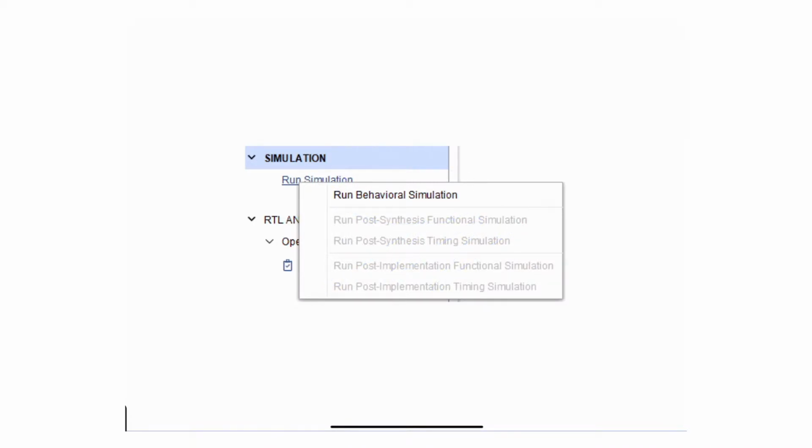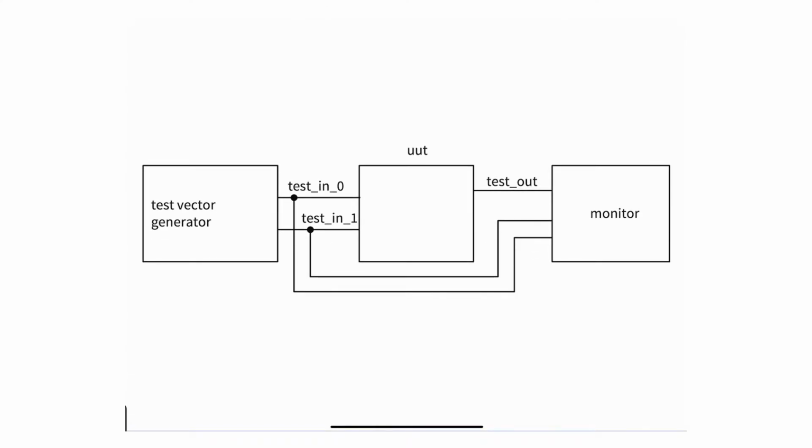So now before I jump into Vivado to show you how we actually run these tests, I have shown you some of the results out of these tests, but I just want to give you an overview of what is really about to happen when I'm writing test benches. Okay? When you're writing behavioral test benches, you're testing the behavior of your code or your design actually. So what you have usually is what we call a unit under test, or sometimes referred to as UUT. What is that unit under test? It is whatever you're testing. So it could be an adder, a subtractor, maybe the adder subtractor circuit that we did shortly. Whatever it is, okay? So you can put whatever you want. This is where your design lives in here. Whatever you're trying to do, you're gonna put it in here.